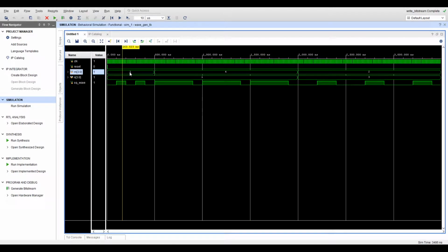At the beginning, you're going to see that M and N are set to 1. That means it's 100 nanoseconds in the on position, and you can see this one is 100 to 200. And because N is at 1, it's also going to stay for 100. That means this one here is 300 nanoseconds in the off position.